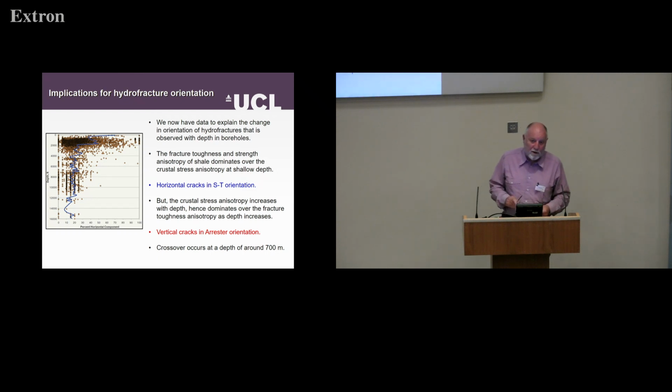Whereas the actual hydrofractures themselves can only produce tremors of very, very low magnitude, if you actually inject that fluid into a large fault that's already highly stressed, you could actually trigger seismicity of much higher magnitude, which would be a problem. And that's why you think you don't want horizontal fractures.